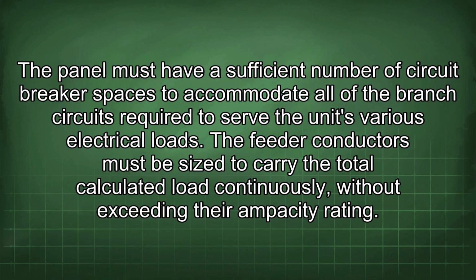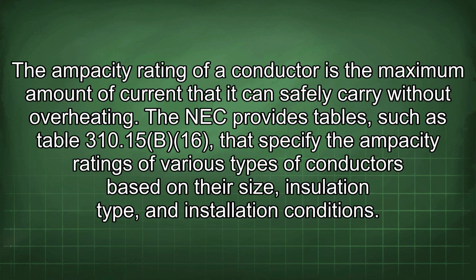The feeder conductors must be sized to carry the total calculated load continuously without exceeding their ampacity rating. The ampacity rating of a conductor is the maximum amount of current that it can safely carry without overheating. The NEC provides tables, such as Table 310.15(B)(16), that specify the ampacity ratings of various types of conductors based on their size, insulation type, and installation conditions.